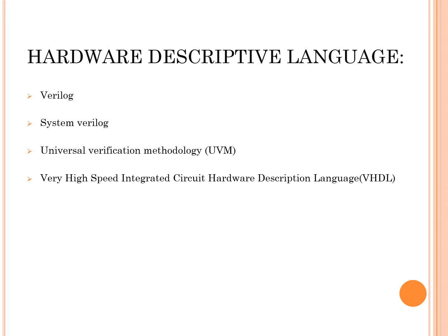Now that we know the basics, let's talk about how we actually describe hardware using hardware description languages, or HDLs. In the VLSI world, the most common one is Verilog HDL, widely used in the industry for digital design. Then we have SystemVerilog, which extends Verilog and is mainly used for verification. This is where we build drivers, monitors, scoreboards, and agents using SystemVerilog classes and interfaces.